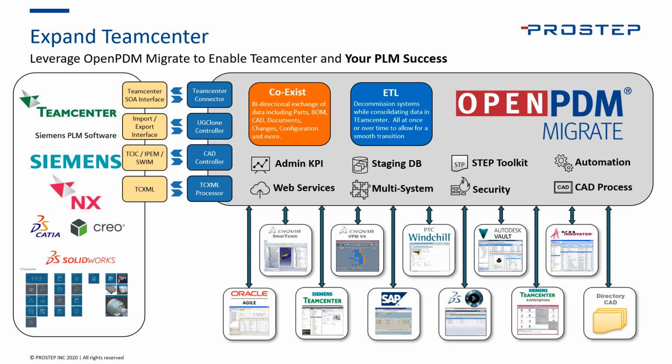We've got our UG clone controller that's now called import-export interface. We've got various CAD controllers for Teamcenter integration for CATIA, IPEM, that's Creo integration, SolidWorks integration, Inventor integration, others. So we have these CAD controllers, and that leverages not just the Teamcenter API, but a combination of the Teamcenter integration API in order to make sure that you're importing this CAD data correctly. And using other interfaces is generally not appropriate for that type of integration.